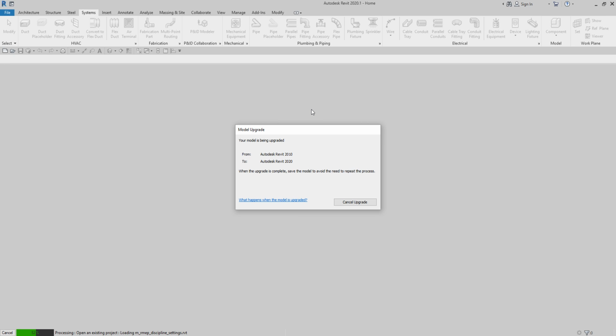All right, so you create mechanical systems by placing system components and connecting them using automatic layout tools. And most of the time, we also use the manual tools to determine mechanical settings such as duct and piping routing scheme to connect system components. So we will be doing that on our next videos.